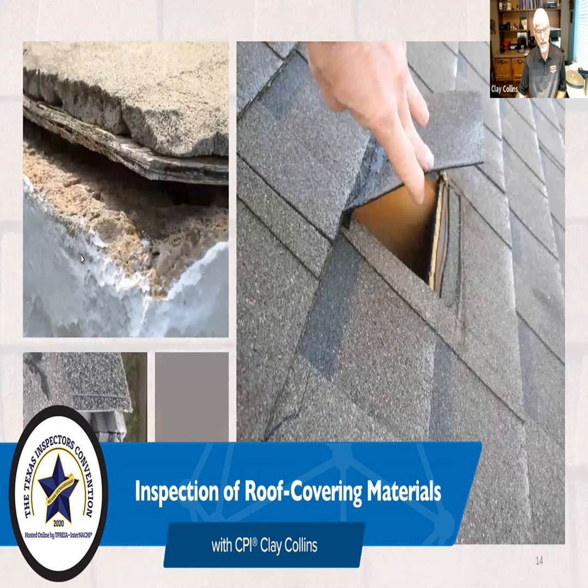Viewed from, we're required to report our vantage point. Where did we inspect the roof from? Well, it says in the standards that we shall inspect it from the surface of the roof, unless, in your reasonable judgment, you can't safely reach it or stay on it, or you're going to damage it. Well, that means the first thing we have to do is find an inspector with reasonable judgment. Sometimes that's a little tough.